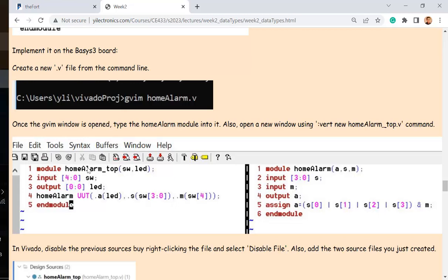So remember the keywords SW and LEDs are in the constraint file. Have you used the constraint file to do anything in the lab? You haven't implemented anything on the board. So probably it's a lab on Thursday. So the switch, SW and LED, these are actually the physical pins on the FPGA board. Just keep in mind. So when you work on this project or this assignment, you have to load that constraint file which has all these keywords and also the physical pin numbers on the chip that are being connected to where, right? So specify that in that constraint file.